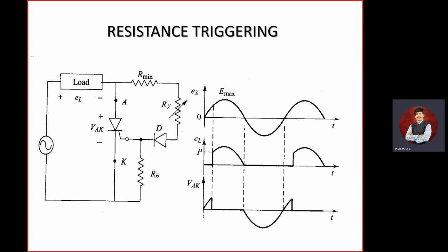We blindly leave the ground and go and check the output, and we do not get the relevant output. So my suggestion is, kindly check the voltage at each element, or check the current passing through each element, so that we can completely come to know what exactly the circuit is doing.